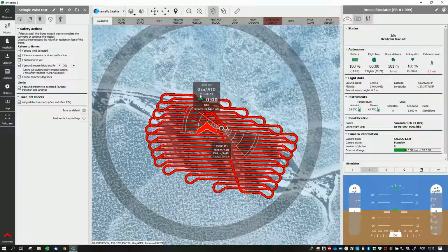Before taking off, I normally turn on the drone once, then turn it off by gently shaking the drone 3 times, just to see if everything is okay. Check if all the sensors are working well, if the Pitot probe is not clogged, has no problems. Also the ground distance sensor, and if the cap is removed from the camera. Yeah, that's it.